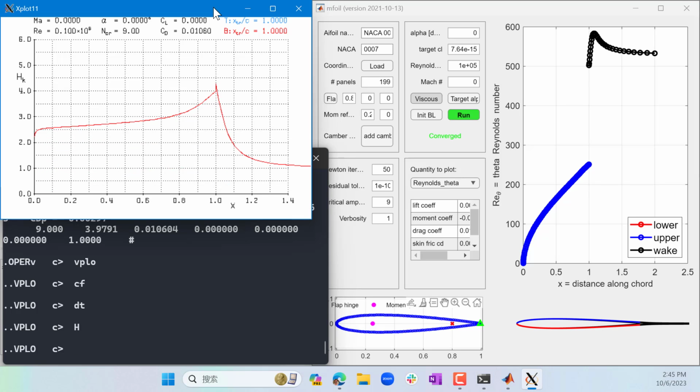Anyway, any questions for now? Yes? Did you say turbulent boundary layer is easier or harder for flow separation? Turbulent boundary layer is more resistant to flow separation, so it separates later. So if you put some roughness upstream to trip the boundary layer into turbulent, it can delay flow separation. And you want flow separation, or you don't want flow separation? Most of the time, if you don't want drag, then you don't want flow separation. We'll talk about flow separation next week.